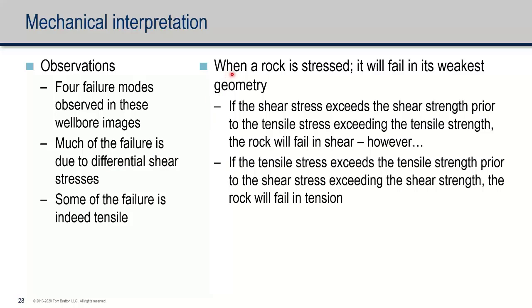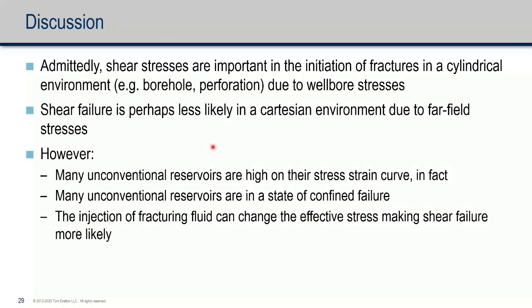So the takeaway message is when a rock is stressed, it will fail in its weakest geometry. If the shear stress exceeds the shear strength prior to the tensile stress exceeding the tensile strength, the rock will fail in shear. Alternatively, if the tensile stresses exceed the tensile strength prior to the shear stresses exceeding the shear strength, the rock will fail in tension. So admittedly, shear stresses are important in the initiation of fractures.